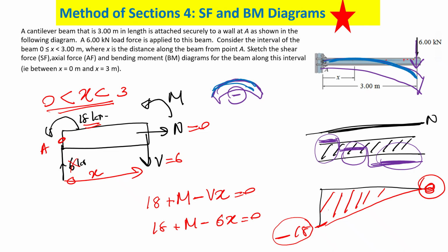And in the previous one especially, some parts are hogging, some parts are positive. Positive means it's bending like a happy face. So in these sections you have to put the reinforcement at the bottom. Makes sense? So it's really important to know how the bending moment diagram, shear force diagram and axial force diagram work, and what the critical points are, whether they are positive or negative. Otherwise we don't know where to put the reinforcement, which material to use, and also which sections are critical. To find all that, we need to know the internal forces. Are we good? Okay.